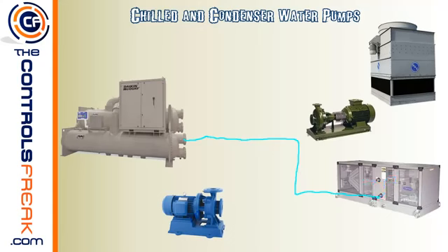Now we want to draw the water coming back out of the coil that's ready to go back to the central plant and get cooled down again. So that'll be this darker color here. And we'll send it this direction. And I'm sorry, pipes don't normally go on a diagonal slant like that, I promise. But it comes into the inlet of the pump. And in case you're not familiar with pumps, if you looked at this type of pump here, the inlet is actually going to be this horizontal one here. And there's an impeller in here, so you can imagine it like a boat propeller, but this is an impeller, that will draw the water into the center portion of it and then spin it around and shoot it out the top here. And this is going to go right back inside to the chiller.